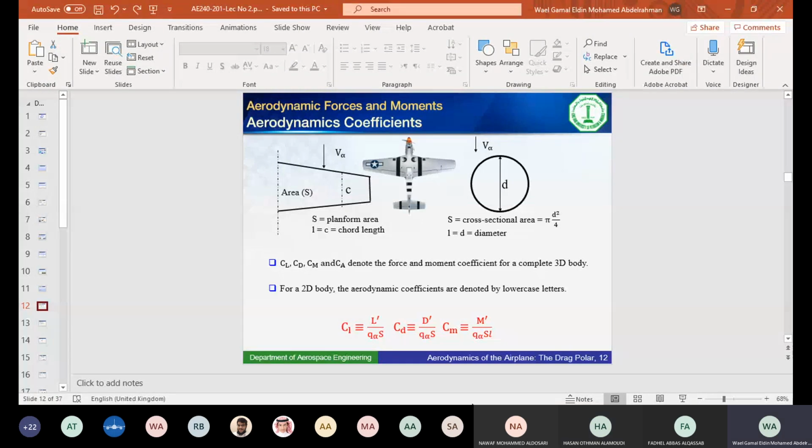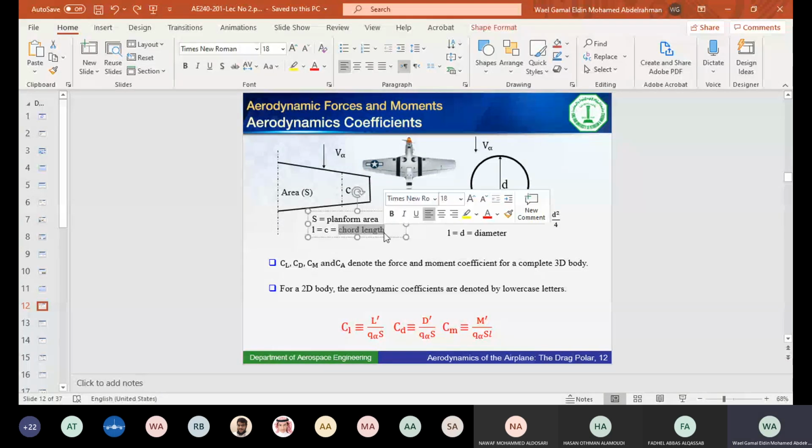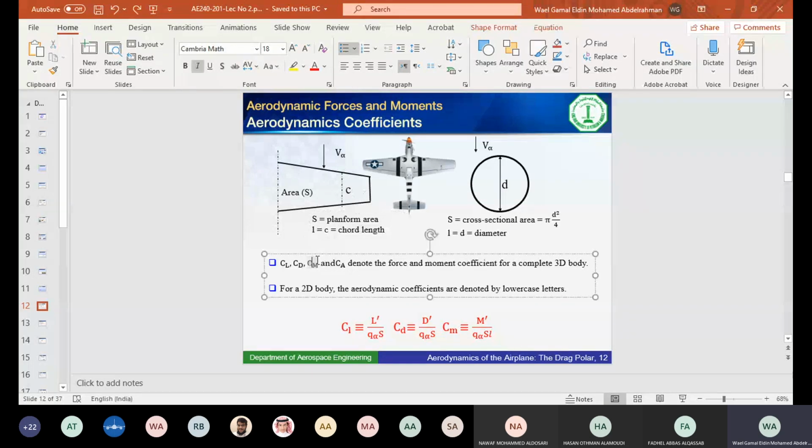Yeah, the airfoil is the cross-section of the wing. What is the length of the airfoil that we use? The chord line, right? The chord length is the characteristic length of the airfoil. When you divide by L here in order to get the coefficient of moment, this L here is the length or the chord of the airfoil, okay?